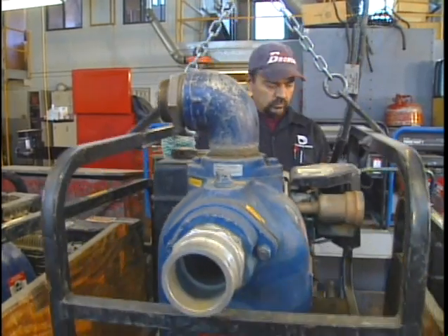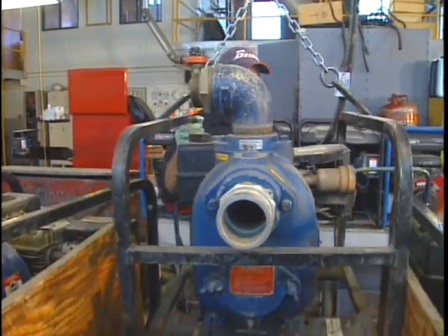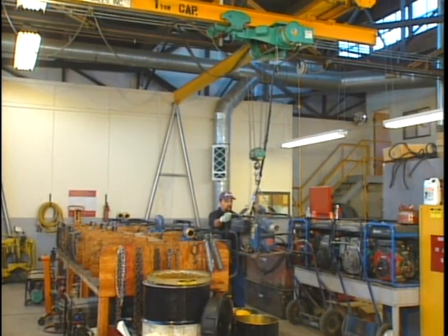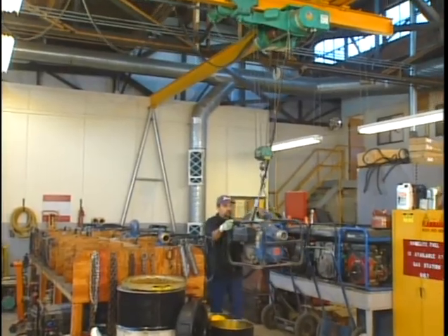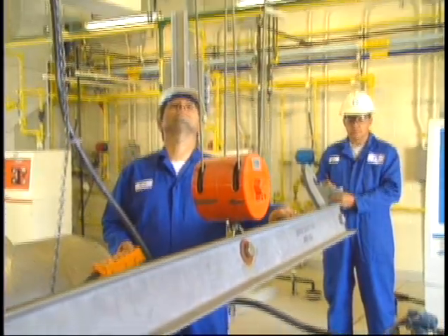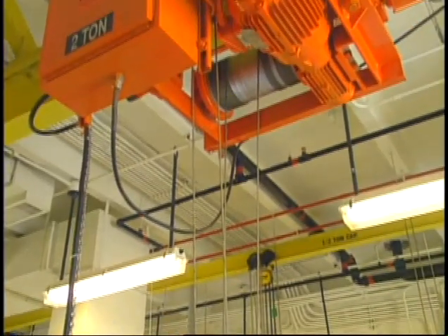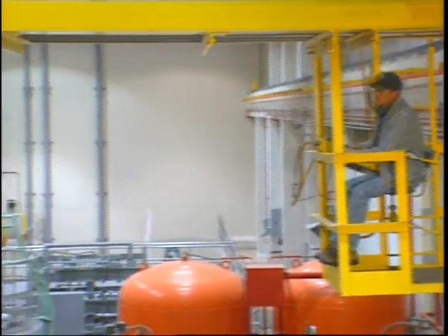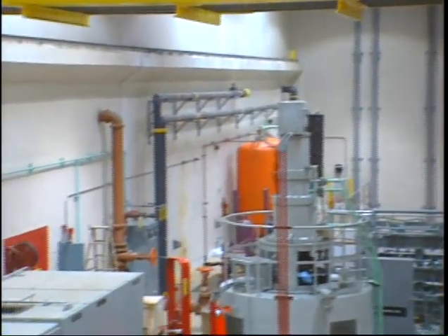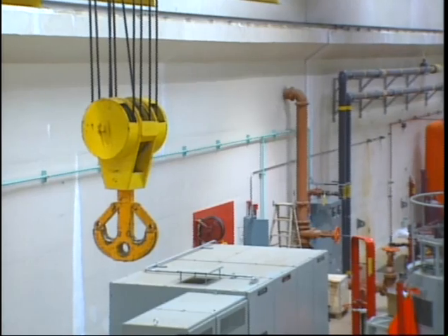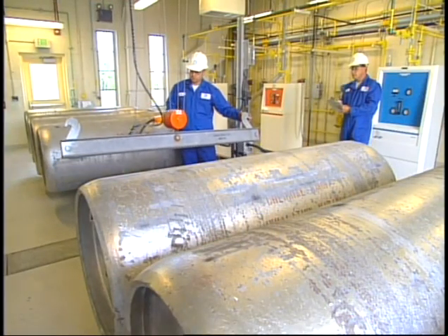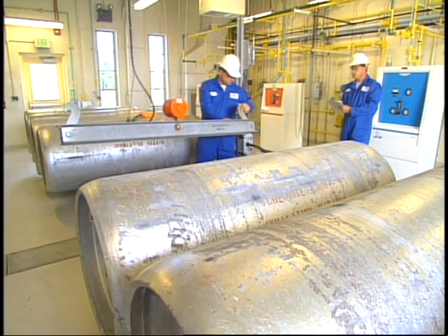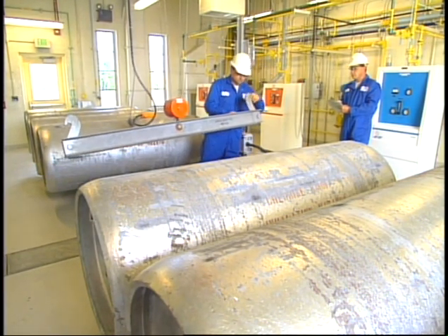Training should include a discussion of proper rigging technique and balanced lift points. The operator should be trained on the specific device he or she will be using so they understand wear limits, braking mechanisms, slip clutches, and any other features of a specific overhead crane. It's important to train on the overhead crane without a load at first to become comfortable with its operation. And finally, training should place an emphasis on maintenance and inspection routines. Proper inspection will prevent mishaps.